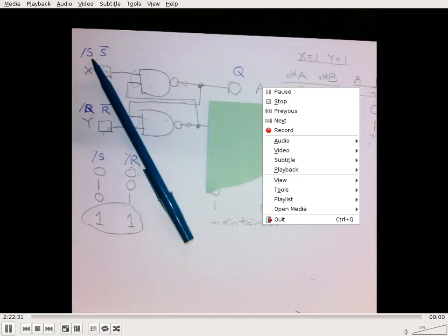A watchdog circuitry is a very interesting one. In many computers these days, there's a watchdog mechanism. A watchdog mechanism is actually kind of like a dead man switch, okay? What it means is, unless the watchdog is hit within a certain amount of time, it will basically say, uh-oh, nobody is hitting me, something bad has happened, I'm going to reset the computer.